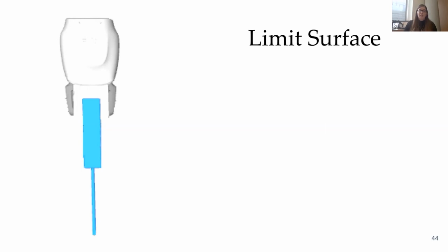If the external wrench lies outside of the boundary, then our grasp will slip because our external wrench overpowers the friction that's provided. Now, the way the grasp slips is well characterized, but we're not going to use that specifically in this work. We're just going to check, does our grasp slip or not, which is, is our grasp maintained or not?